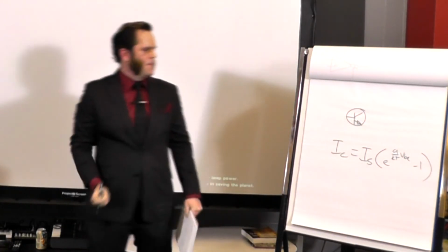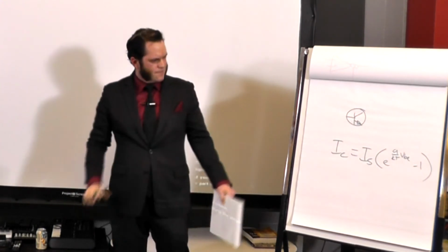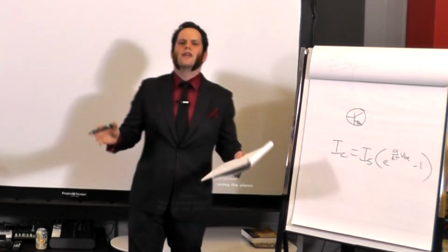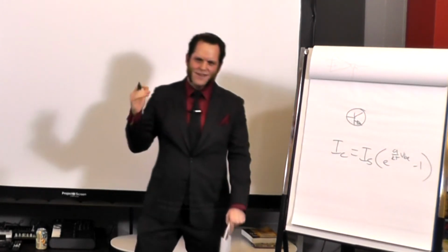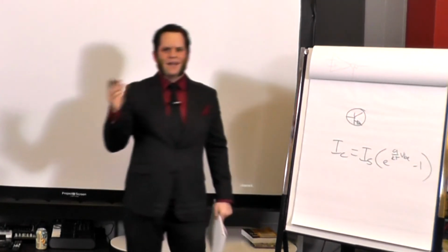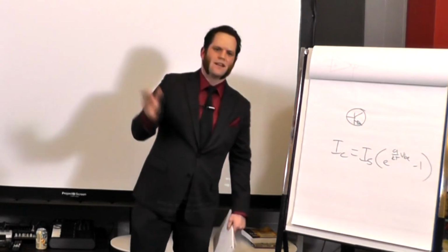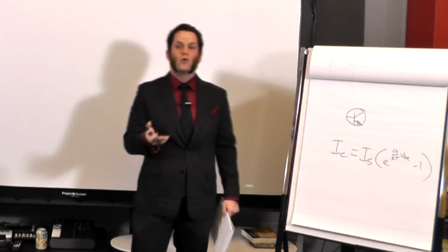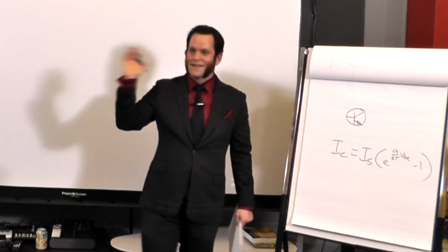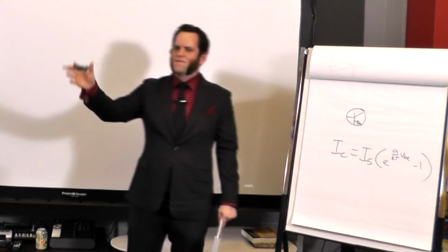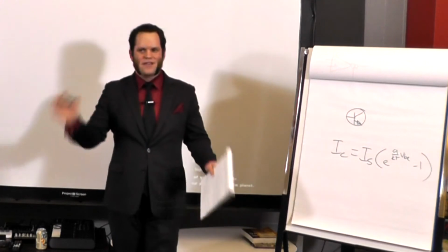So we can do that, and it's generally okay for VCAs and things where we're not super sensitive. You can shift something by a decibel and you might pick it up, you might not. But you shift something by 2 hertz and all music is way off. Just a little bit of beat frequencies going on, it's a mess, nothing sounds in tune.